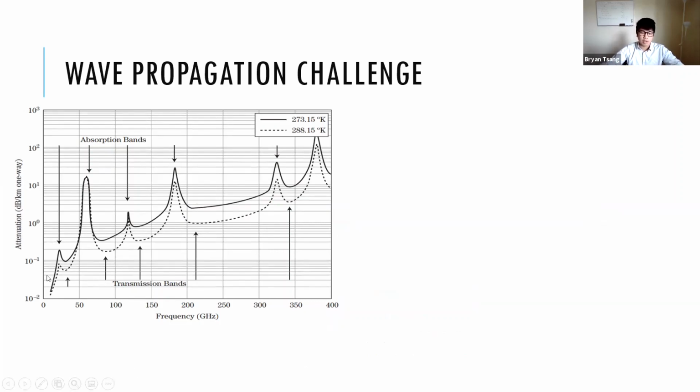Basically, what I really wanted to show was this increase in attenuation versus frequency. So for 5G, we're really only looking at this segment, but even at those millimeter waves, it's still much more attenuation than at those low bands. And this is what allows us to communicate really far using that low band 5G versus the millimeter wave.